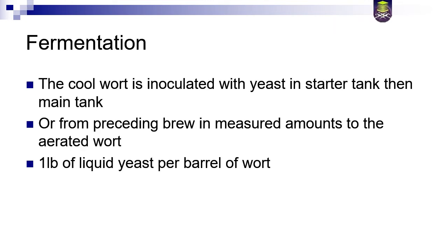Okay, fermentation. The cold wort is inoculated with yeast in a starter tank, then the main tank, and we proceed to brew in the measured amount into the aerated wort. One pound of liquid yeast per barrel of wort. That's the quantity of yeast used inside the fermenter.